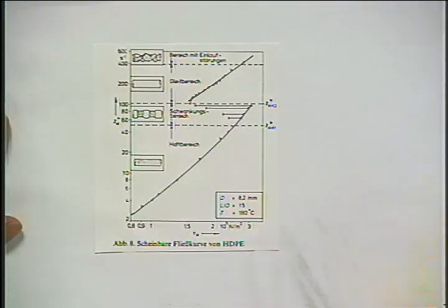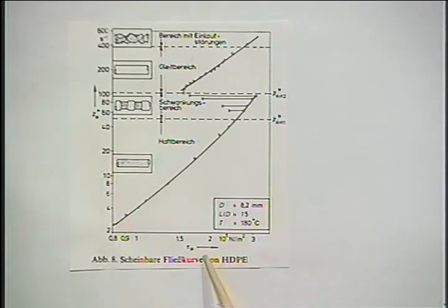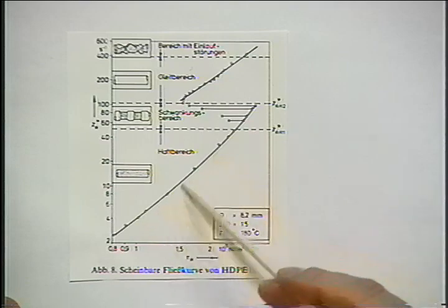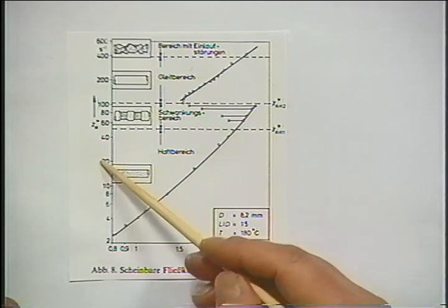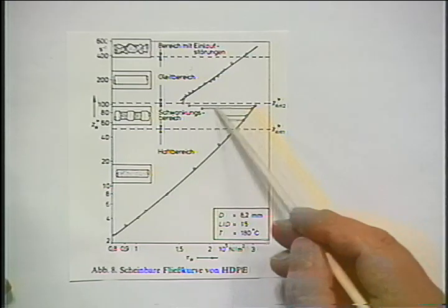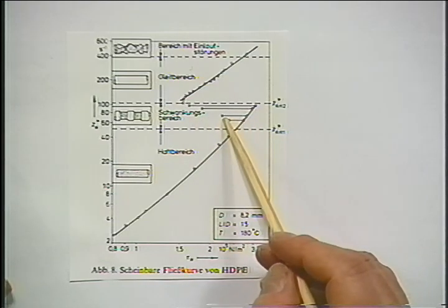The extrudate itself is regular at low rates. This is again our flow rate versus pressure drop curve in some normalized fashion. So at low rates, this relation is quite normal. At higher pressures, you get higher rates. But then when you exceed a certain stress level, it starts to pulse back and forth. That's where we had these irregular pressure profiles before.